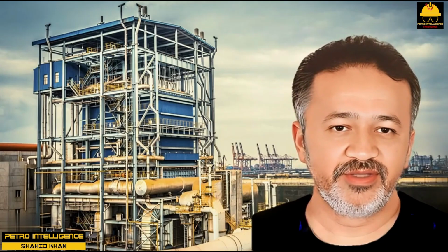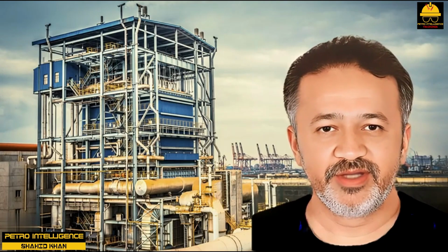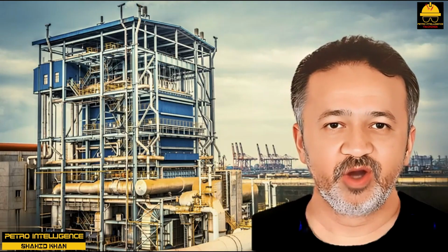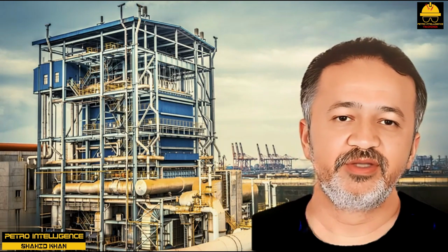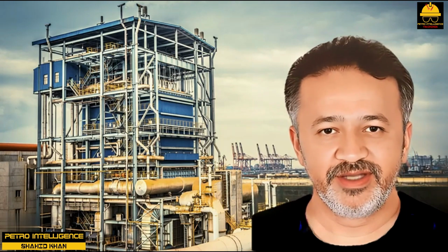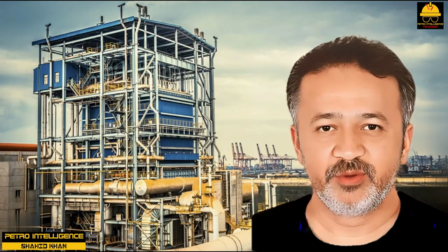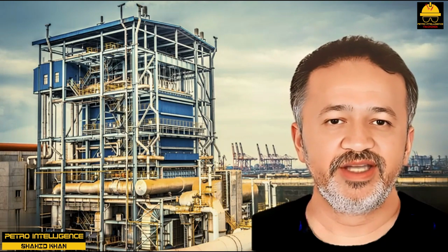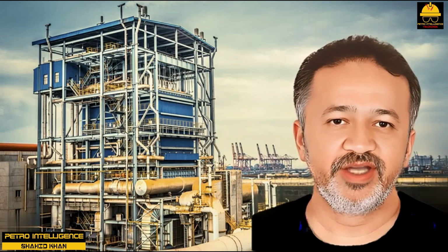Fixotal tube insert. The Fixotal tube insert is a metallic coil, which is static and self-tightening inside the tube. There is no intended mechanical cleaning effect with this insert. The concept is to increase turbulence in the tube side flow, especially at the tube wall, by constantly mixing slow-moving fluid near the tube wall back into the bulk, thus increasing tube side heat transfer rate and reducing fouling.